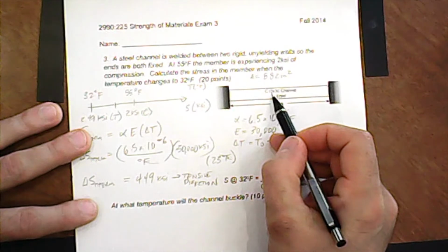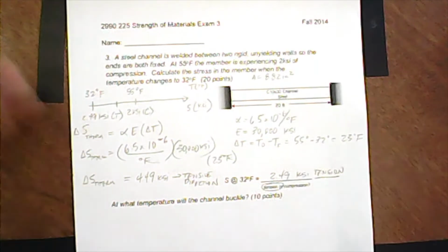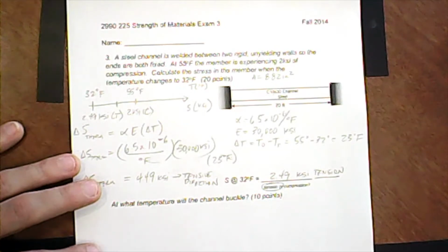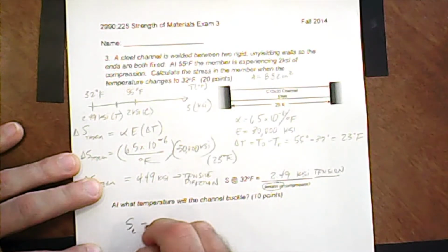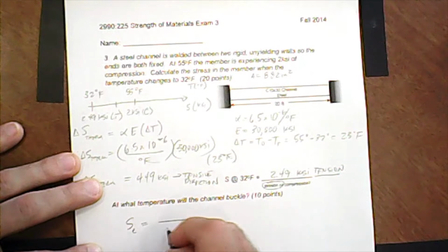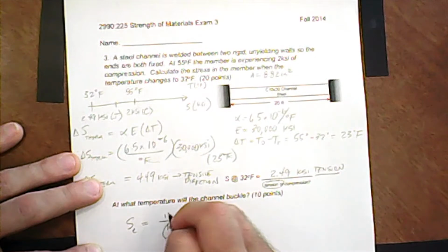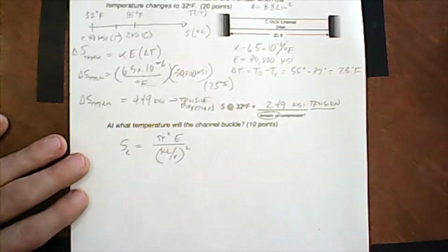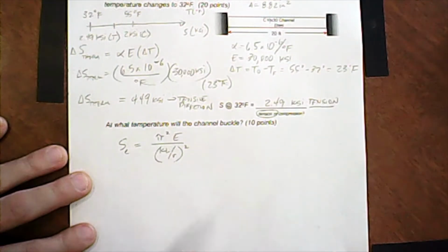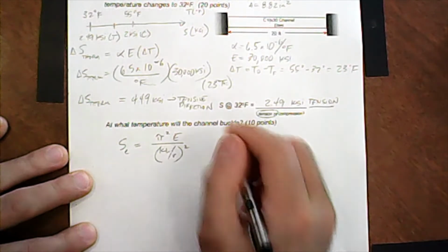And we're going to have an Rx and an Ry. Remember, we're going to take the smaller of the radius of gyration. In fact, let's talk about real quick what the equation is, because that's important, isn't it? So the equation for the Euler buckling stress is going to be: you're going to have (KL over R) squared in the denominator, and in the numerator we have pi squared times E. Okay? Those are all pretty simple things, right? Pi squared, interestingly, the only place I know about pi squared, it's usually just pi.